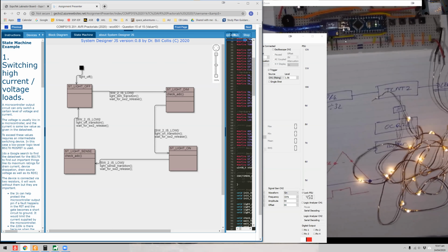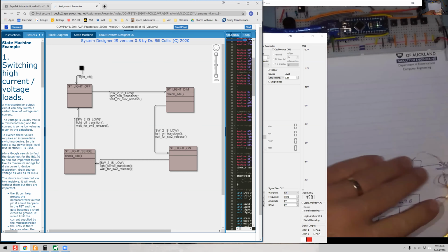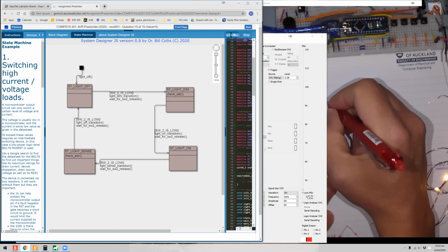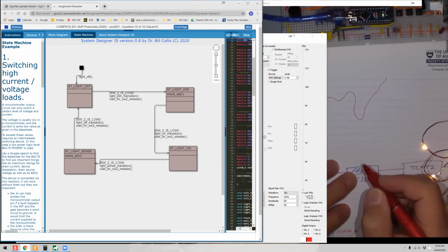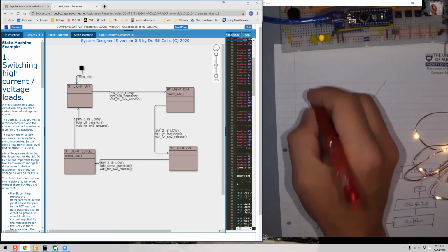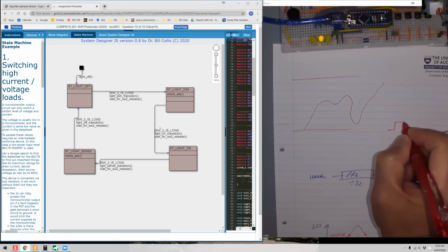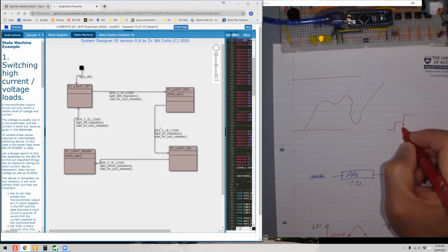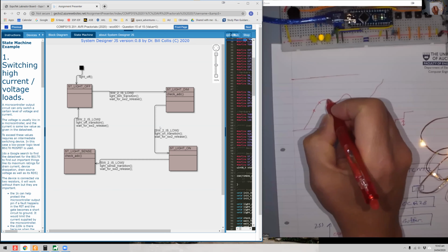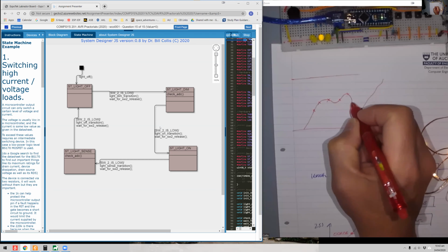I'm going to tell you a little bit about analog to digital conversions. And the way I want to do that is just exhibit to you what's happening with an ADC. So with an ADC, when we're doing a conversion, we've got this linear value doing whatever it's doing. And then what we're doing, let me just get that out of the way. We've got some voltage, but what we're getting out of it is a stepped waveform. So this is our voltage resolution, right? And the other thing, of course, our ADC can only do so many conversions per second. So we're actually only taking samples at certain points in time.